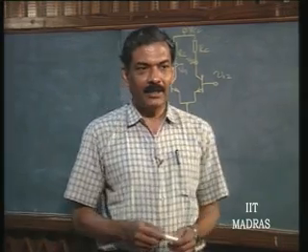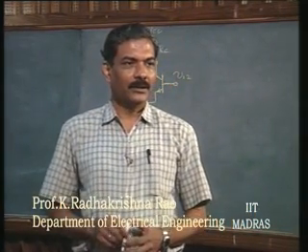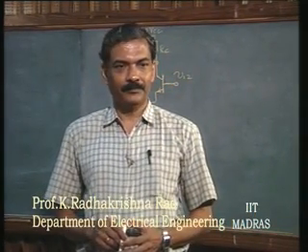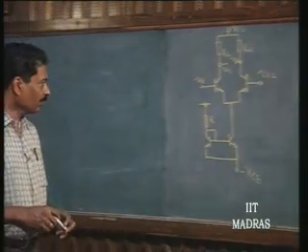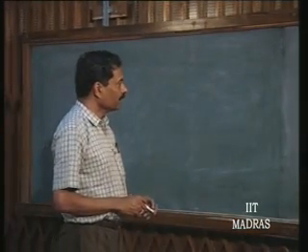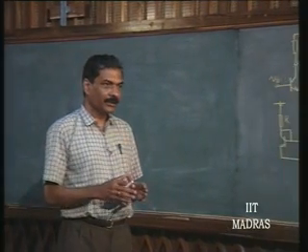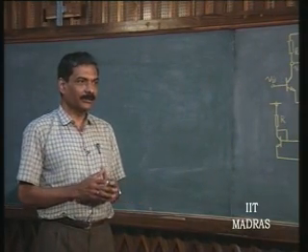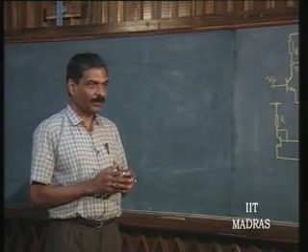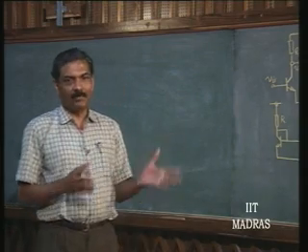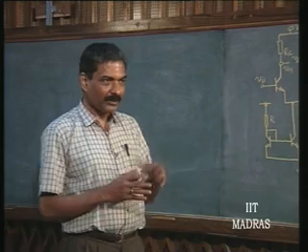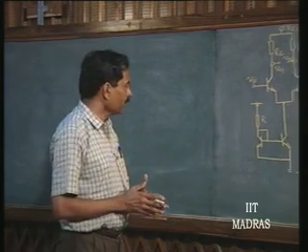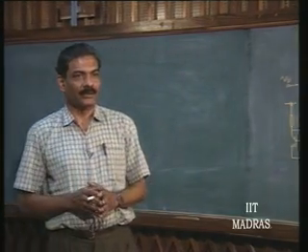So, in the last class we were discussing the differential amplifier as a basic building block, and we saw how it can be thought of as a stage developed as an alternative to the discrete circuit common emitter amplifier configuration, with all sorts of bypass capacitors and coupling capacitors removed altogether and replaced by transistors.